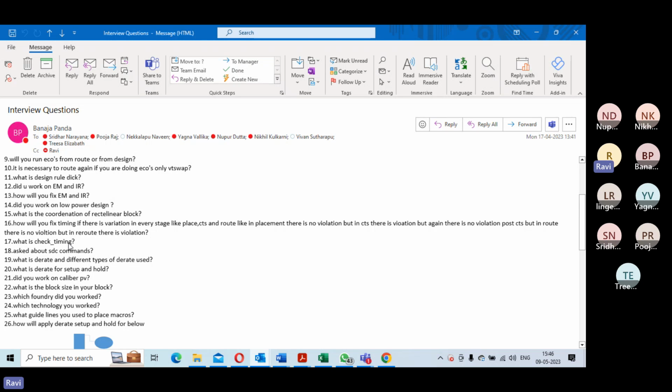You may not know set clock sense, we will talk about that. Not to worry, but at least you should say create clock, create generated clock. Okay. And then you can set clock uncertainty. For clock, you can give set clock transition.